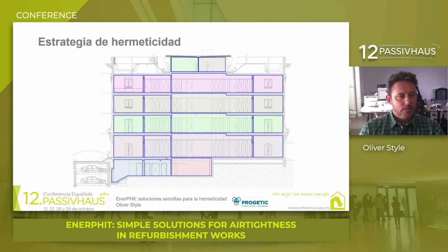Firstly, to facilitate airtightness pre-tests using a single blower door machine per floor. That is, as the different spaces were all sealed between floors, we could test each floor, provisionally closing entry doors, etc., to be able to detect, correct, and identify infiltrations on each floor.